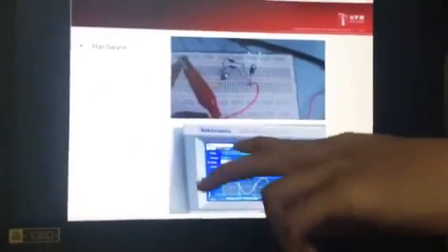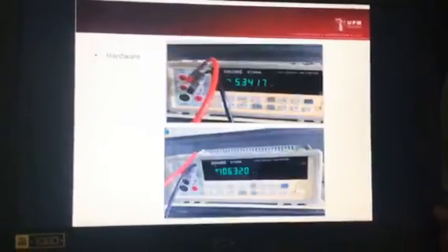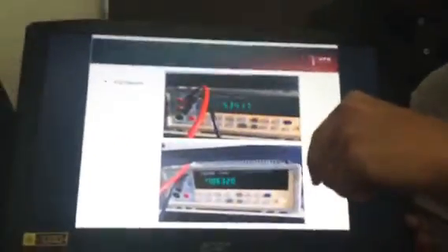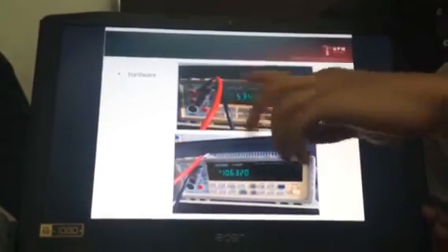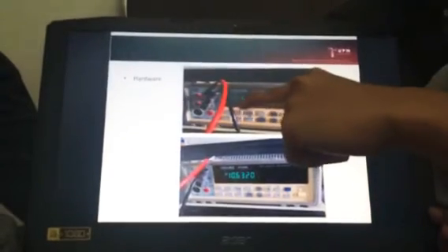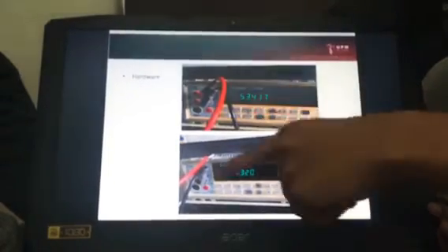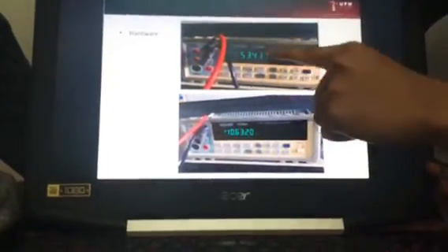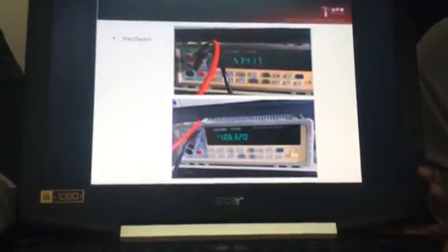Here is the AC voltage input, 15 volts, and we are using a multimeter to see the values of input and output. For the AC input, using some formula, we get the peak value, which is 5.34. Then we can see the output value over here, which has turned to DC, 10.6. It means the value is 2 times: 5.3 times 2, we get 10.6. No loss, no worry.